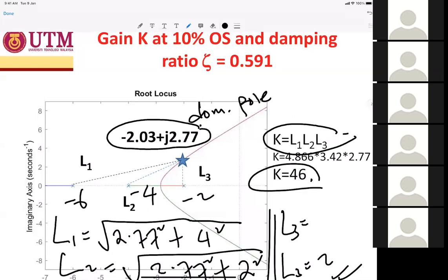Okay. Thank you, doctor. Any question? Doctor, I have a question. Name? Tekpal. Tekpal Gil, yes. Regarding the additional zeros, what does it mean by a positive zero? Does that mean a positive zero is a zero on the right half plane? Positive zero means the zero is on the right half plane. Negative zero means the zero is located on the left half plane. So if a zero is on the left half plane and near the dominant pole, it will go faster. And if it's on the right half plane, it will go down and then come back up. Yeah. Thank you, doctor.